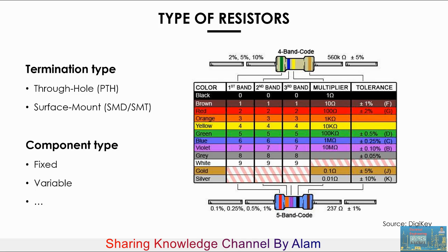In this lesson we're going to learn how to read the value of a resistor using its colored bands. So we're talking about through-hole resistors here, and we're going to use this table to determine the value of the resistance and the tolerance. A resistor can have a 4-band or 5-band code. Let's start with the 4 bands, that is the simplest. In the case of the 4-band, you can notice right away that the bands are split into groups. We have the first 3 bands in a group all the way to the left, and then we have another band that is isolated. So the first 3 bands are used to determine the value of the resistance, and the last one will be used to determine the tolerance.